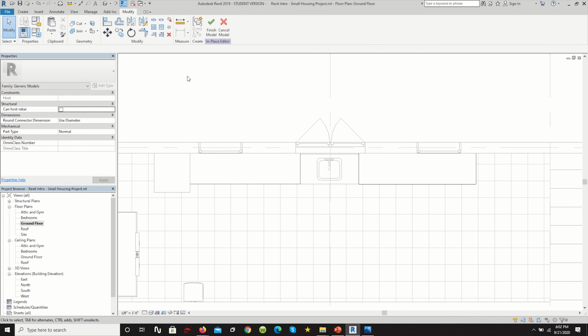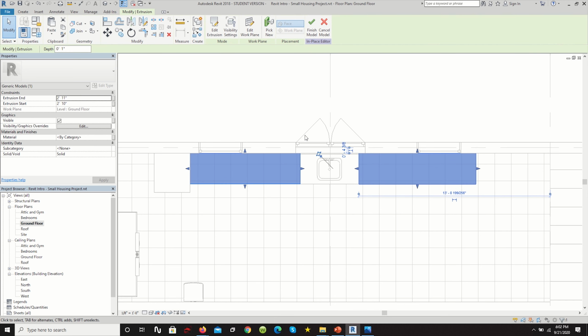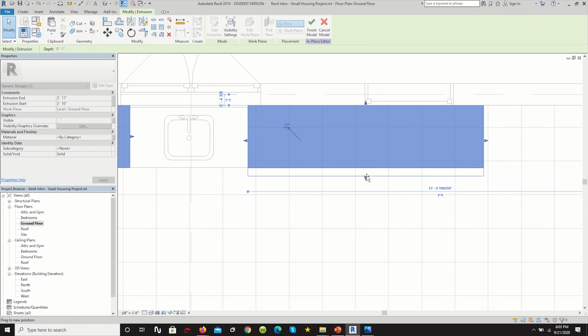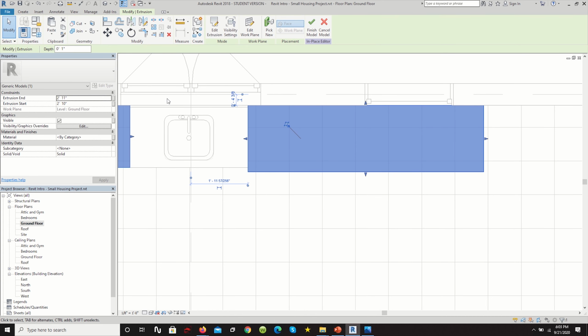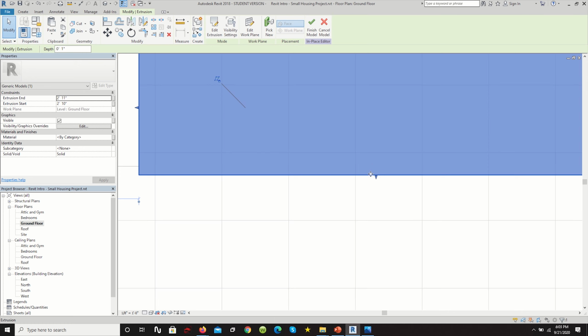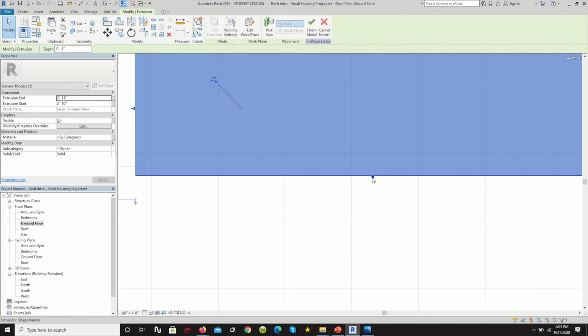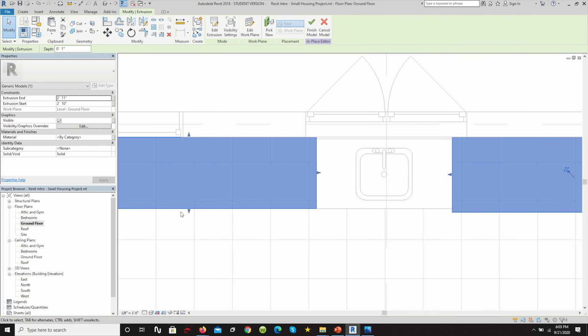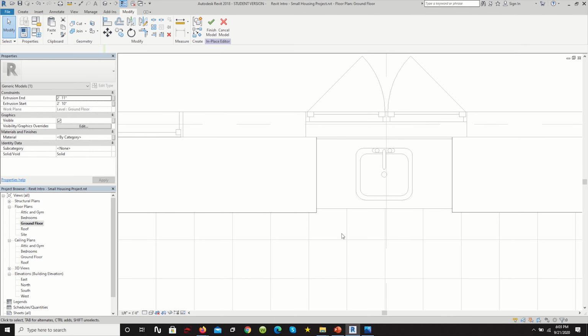What tends to happen is, while you're modeling in place, if you model 2 objects together like that, Revit is going to group them together. So just be mindful about that. What we want to do is actually extend this about 1 inch, because countertops tend to have a nose, a little lip that hangs over the cabinets beneath. So we don't have to make it super accurate, but let's extend this about 1 inch. Let's do about the same amount here.